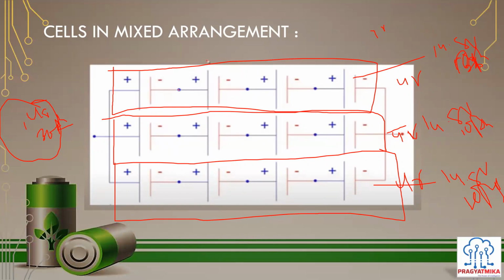See, the thing is that respective to the BMS, the balancing we have raised was a valid point. Construction and everything is similar, and that does not make much of a difference, because you have to join all of the terminals. The thing is related to the BMS. In this series-oriented approach, we get the flexibility, or the opportunity, to monitor each and every cell, because as an input to the BMS at a cell level, we can only measure the terminal voltage, or the open circuit voltage, whichever we consider.